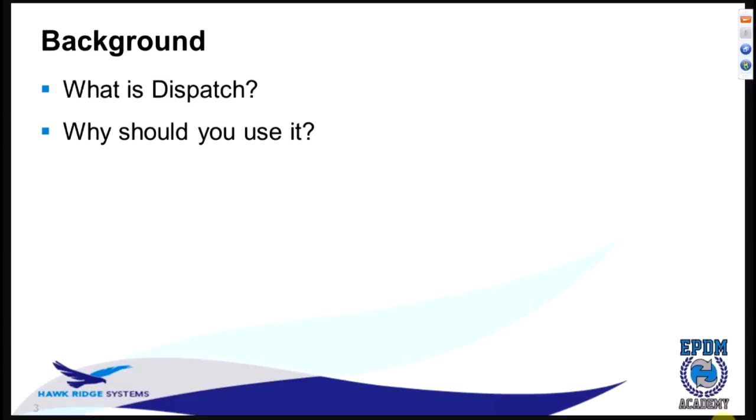So, what is dispatch? The way I like to think about dispatch is that it is the middleman, or the intermediate step between the out-of-the-box capability of Enterprise PDM and the full-on API coding. You've got your out-of-the-box functionality, everything that you can do in the admin tool, and then EPDM has a fully open API, so you can code basically most anything you can think of to automate some process in EPDM.